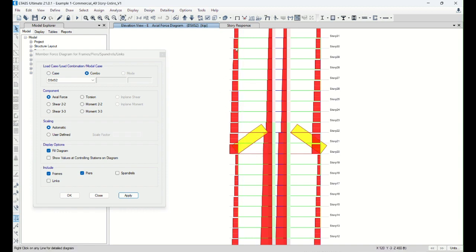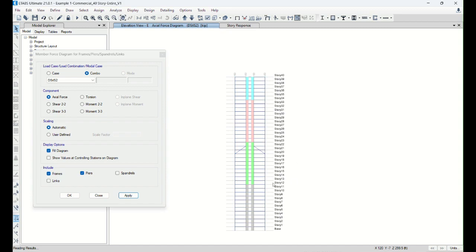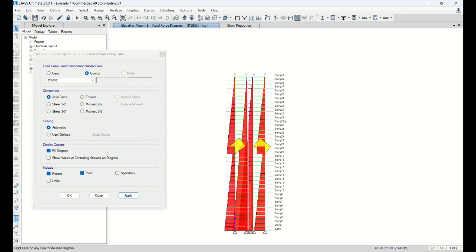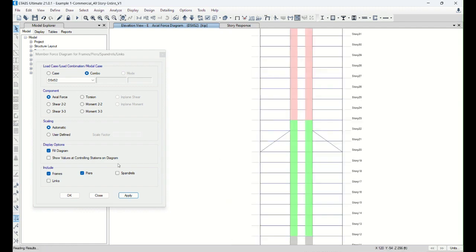Previously, this compression force was continuously growing, but now because of these sizes, the bracing elements are holding it back to the core wall, so a lot of tension develops here, which means less compression force going down. So with this model, obviously, if you use this current model, you have some kind of issue.